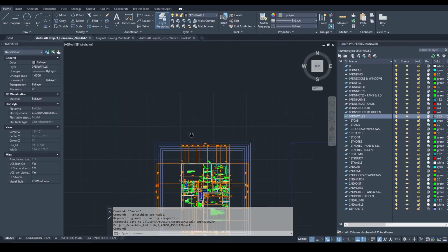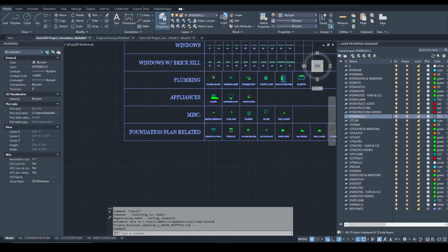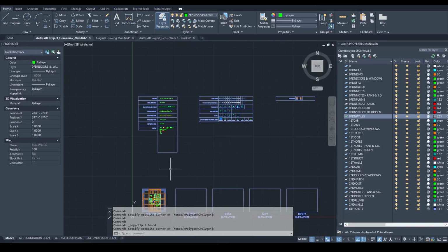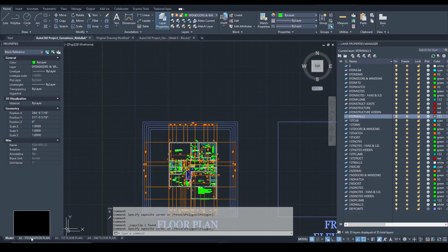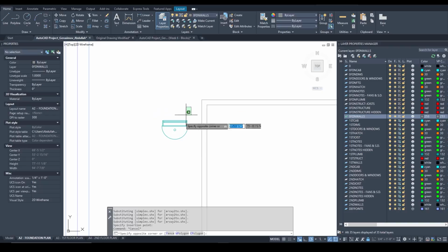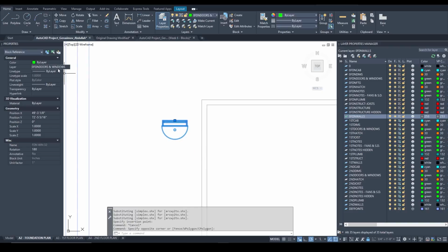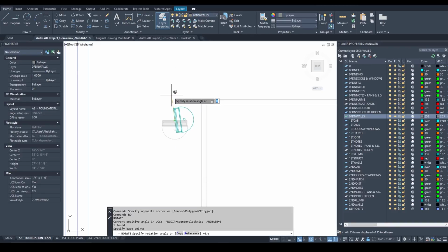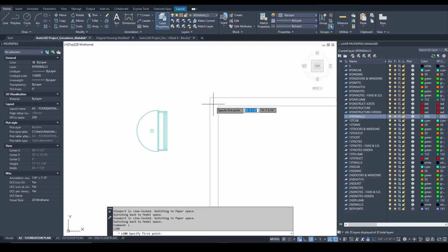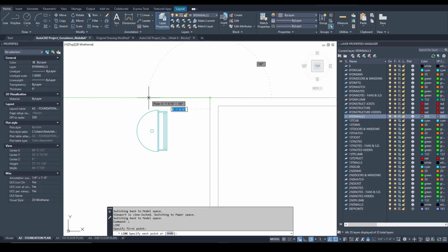Next, let's place our window and the well according to the PDF. Go to the model space where your blocks are. Select the foundation, window, and well, and Control C for easier copying. Go to the viewport, Control V, and it will appear here since it's already been assigned to the correct layer. Now let's rotate it, RO, select anywhere, and try to make sure that the rotation is at the correct angle, like this one. Since we're supposed to put it roughly